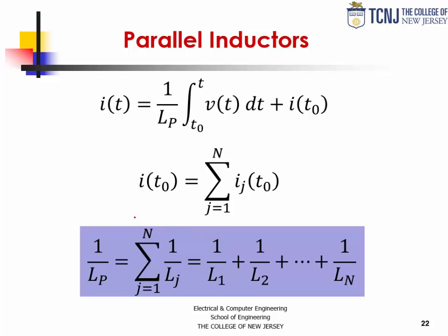Keeping in mind that for inductors as well as capacitors, you have to account for any initial energy stored in the device. In the case of inductors, it would be any initial currents in the inductors. In the case of the capacitors, it would be any initial voltages in the capacitors.